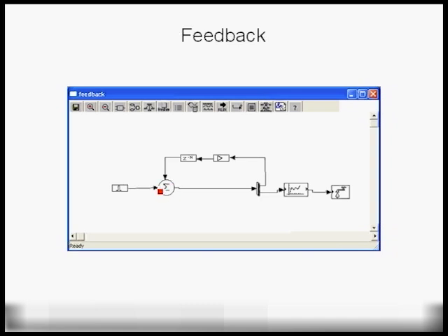Here we have the add block, which basically adds its input blocks. And here we show the node block, which takes its input data samples and forks them out to the output samples. And we're implementing a low-pass filter, so it takes the sample, it feeds it through a gain, in this case, for example, 0.9 or something, minus 0.9.